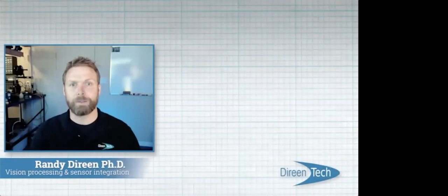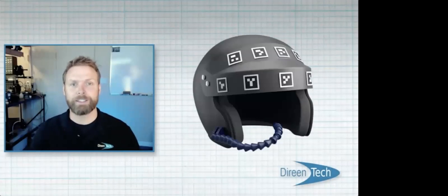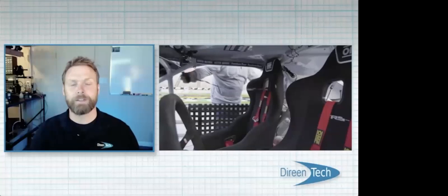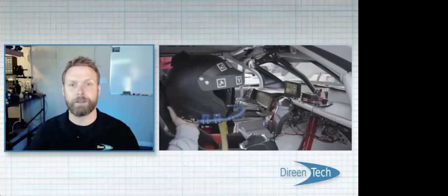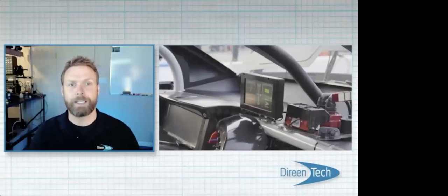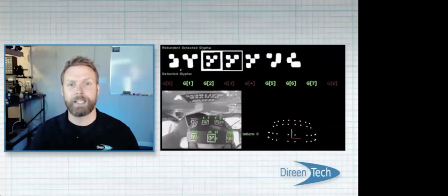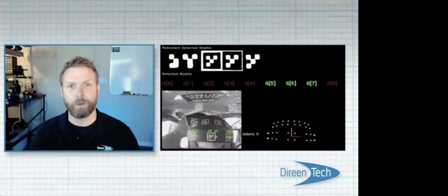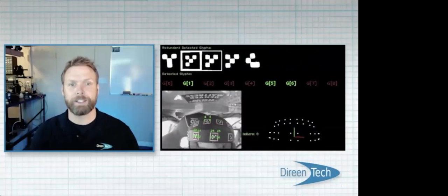The video you just saw was of a NASCAR we adapted to be controlled by a person with quadriplegia. Steering is controlled by tracking head position with respect to the car. We do this two ways. First, we have a gyro attached to the head and a gyro attached to the car. We combine this information to get a high rate head orientation with respect to the car. Second, we track the head using a camera at lower rate. The two orientations are then mixed together via Kalman filtering techniques.